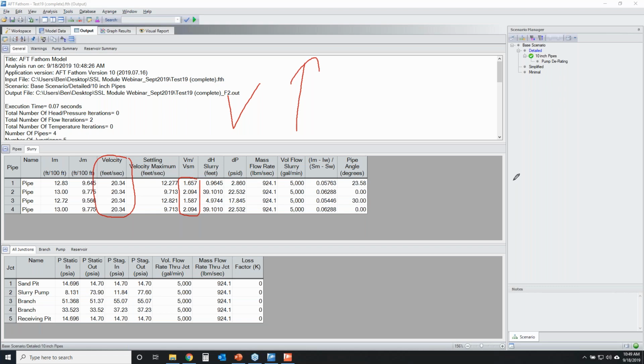That erosional velocity has to be there for a long period of time. So it's more of a transient thing for how long your velocities have been operating at a very high rate, which is going to start to erode your pipes. So this is where you have to find a balancing act, and you want to make sure your velocities are high, but not too high.